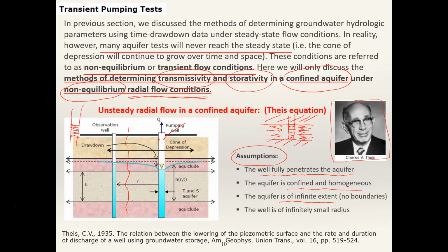So those are the boundaries. So we assume that the aquifer is of infinite extent, infinitely large, meaning that there are no boundaries. That is a major assumption. It may not satisfy the existing boundary conditions, the existing site conditions. So in this lecture note, I have added some slides near the end that will show you how to handle this kind of complex site conditions.